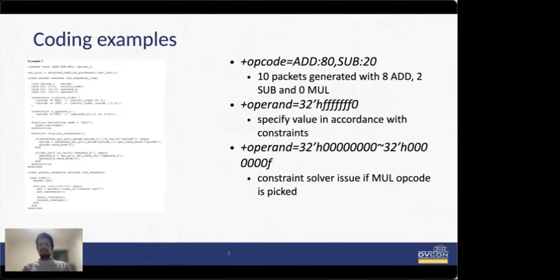context. So I'm trying to use most of the constraints which are written by calling it in the pre-randomize and turning off the rand mode, but still letting the constraint be solved. But in these scenarios, you might want to consider even turning off the constraint mode for a particular constraint line.